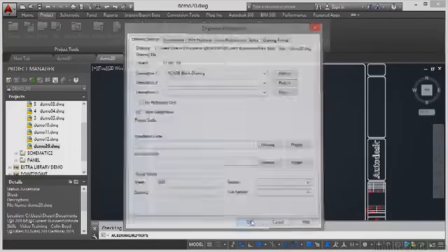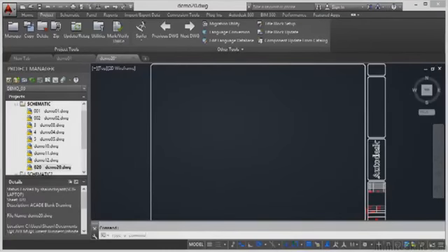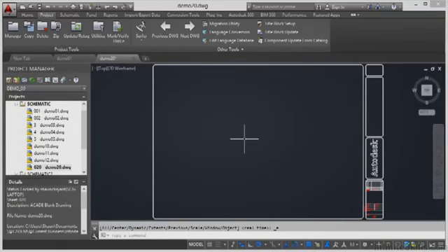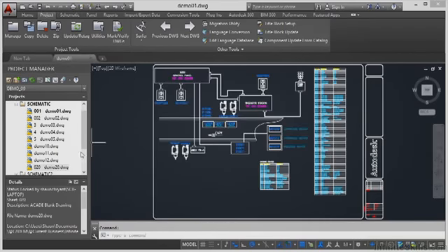So I'll OK that now, update, and you'll see now, there you go, sheet 020 and description ACAD E blank drawing. What I will do as well, I'll just double click on the wheel there just to center that and to zoom extent. I can then save that drawing, and then I'll close that drawing. Notice it's not bold anymore, and it displays the sheet number as per the settings we set previously. Notice the details pane doesn't update until I double click on a drawing, like so. So now that's sheet 001 and it's back to the flow and interconnection diagram.